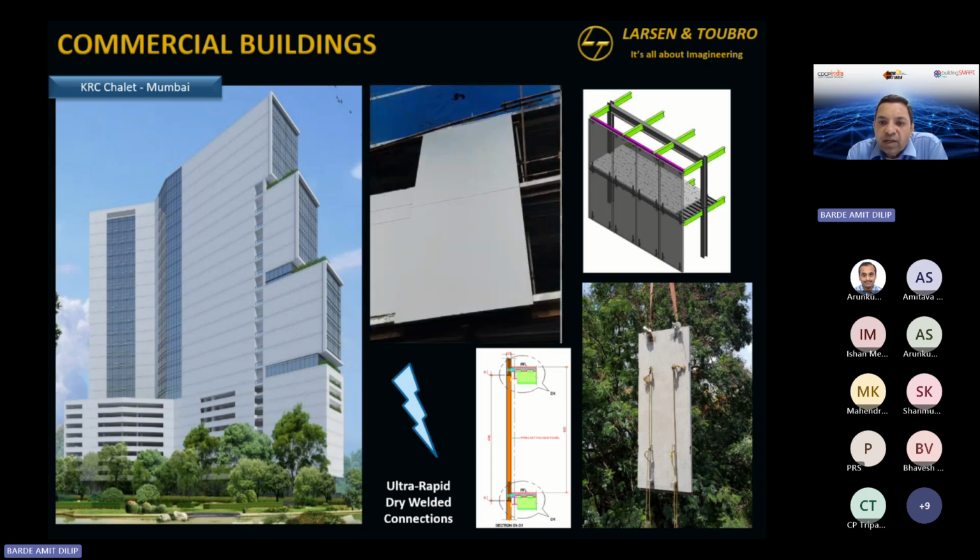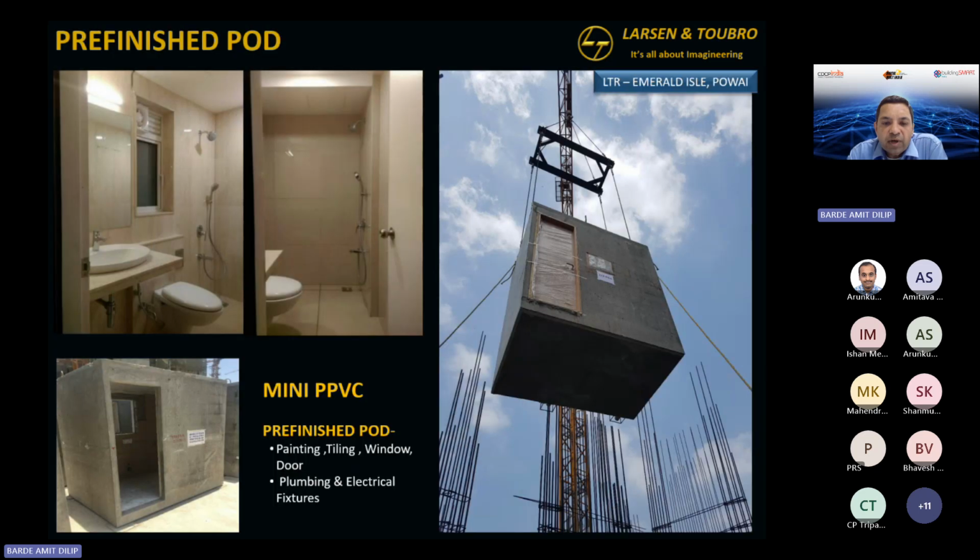But what will take equivalent block work of about 3 days, including your plastering, painting, in about 20 minutes, we are able to attach this panel to the structure and move forward. Right? And then there is no issue of plastering, seepage, joints, and all that. It's a solid, I think, M40 grade above concrete panel, which will work better.